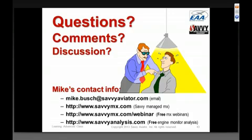Mauricio is wondering, if I keep my CHT under 400 degrees, do I have a red box or red fin? Well, if you keep it under 400 degrees, then you're staying out of the red box. Whether you have a red box or not depends on what your power setting is. But as long as you're keeping it below 400, which is sort of where we define the edge of the red box, then you're staying out of the red box, which is what you want to do. If you run enough power, there's always a red box, and if you run little enough power, there's always no red box.